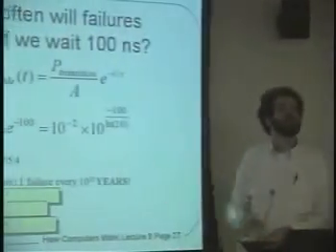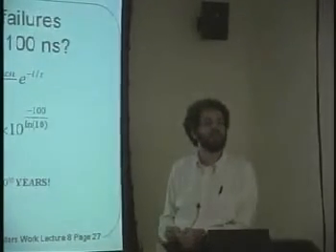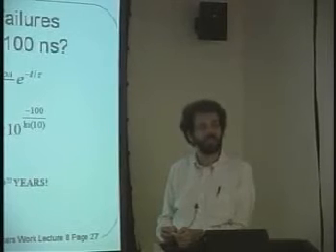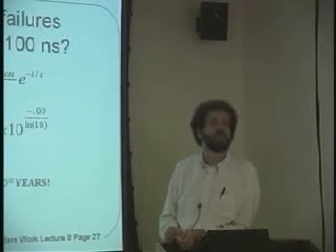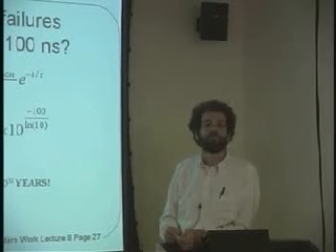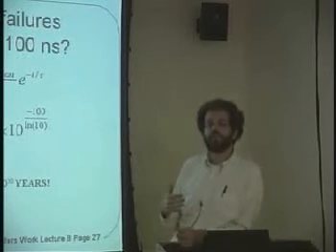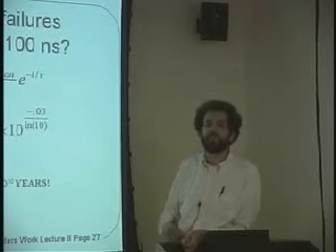And the amount of time you need to wait, if we're going to wait for this long, and this, by the way, is the typical length of time that is used. If you talk to any digital engineer that's out there and you ask them, how long do you wait for a metastable state to resolve itself between one state or the other, the answer is 100 billionths of a second. Okay, that's how long we wait. But aiming at 10 to the minus 45th is completely excessive. It's totally crazy. But it turns out that you have to wait 30 nanoseconds at least. So the idea is, well, if we're going to wait for that long, we may as well wait for 100.